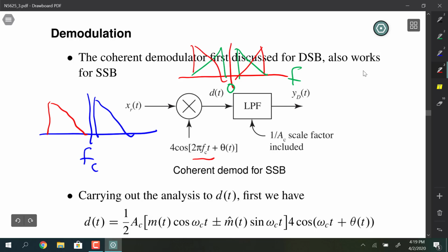Basically, they'll be overlapping like that. Is that believable? Okay, it's pretty cool. You ought to run the experiment without the bandpass filter in there, at least for yourself, to verify that you get another signal landing on top. It will be inverted spectrally, so it won't make any sense. It'll sound like a foreign language, worse than a foreign language. It'll just sound like nonsense because it's spectrally inverted.